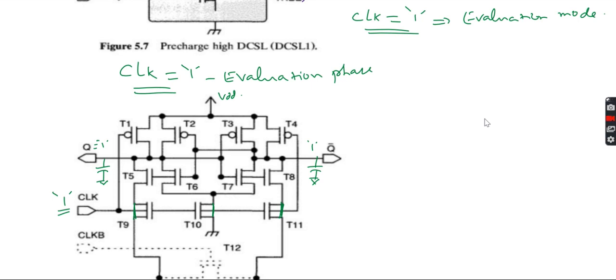Now when this transistor is on, this is on, next what will happen, this will be a 1, correct? So here Q is equal to 1, which means for this inverter, this is 1. If this is 1, this is the inverter, so the output will produce a 0 over here. Or I can say if this is 1, this transistor will be on.